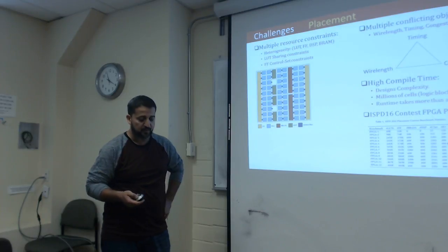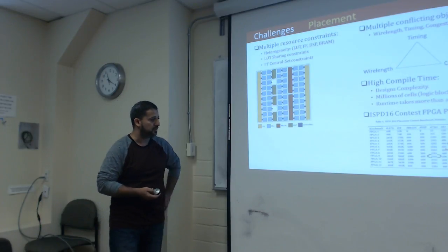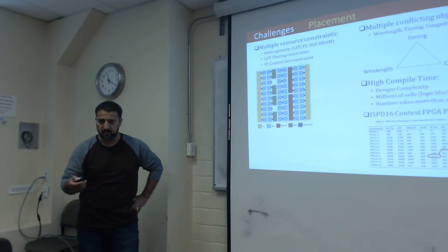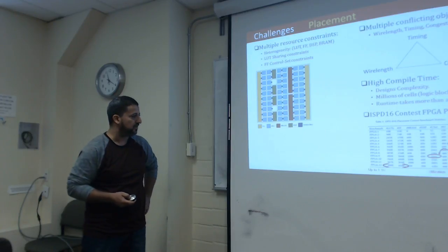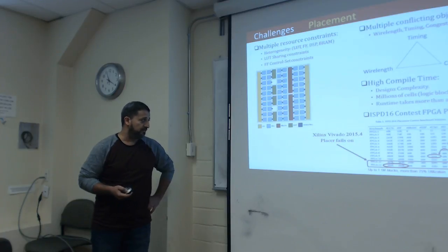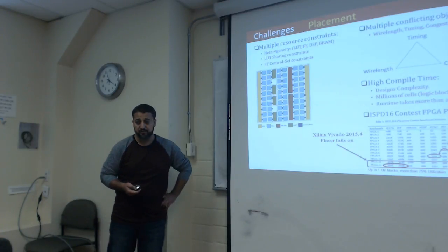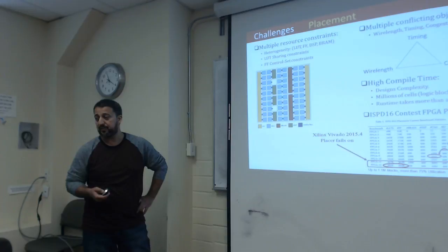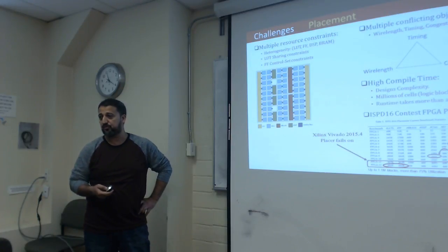The benchmarks are complicated for routability, with high Rent exponent, a lot of combinations of control signals, and large utilizations. Even Vivado 15.4 fails to produce a routable solution for the largest two benchmarks.